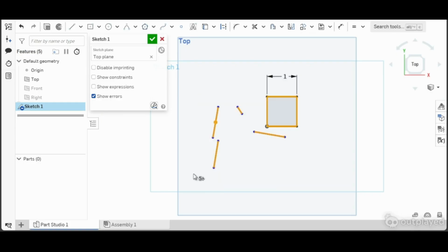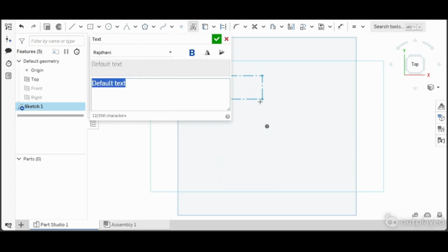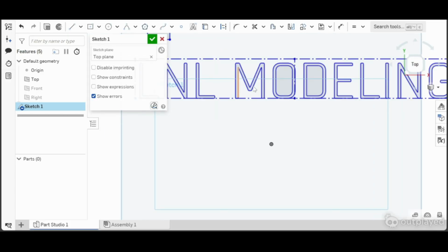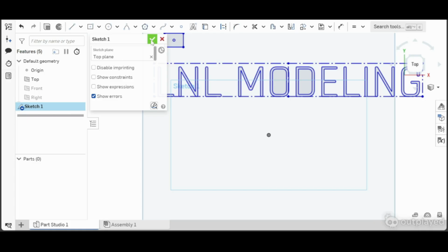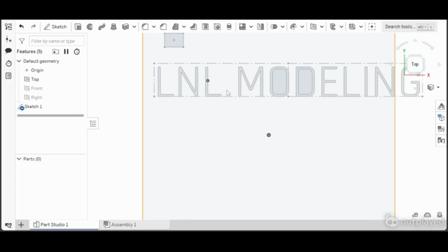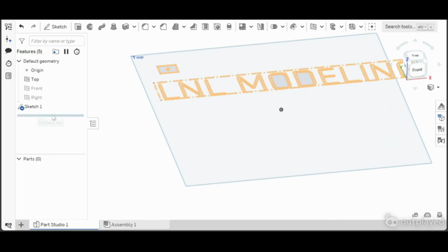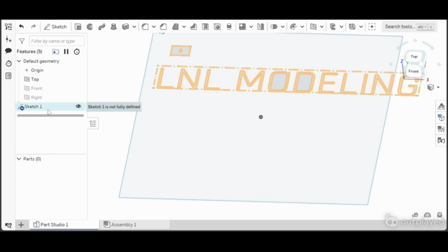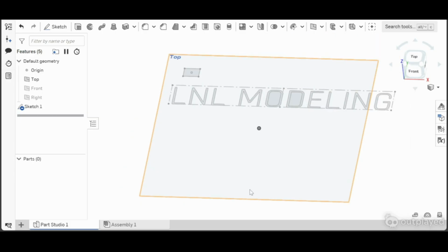Sorry about that. I can make it say this, and when you're done, you can click this green check mark. And then that's your sketch done. You'll see it populate in your features menu, even though it already was, but now you'll be out of it. And then congrats, this is your first sketch. In the following videos, we'll be showing you how to take this thing from the 2D plane to the 3D plane. Until then, I hope this has helped, and thank you for watching.